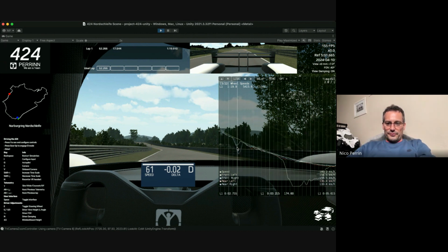135 kph, 133 for the rears, where the car is at 180. So the rear wheels are going 45 kph slower than the car. It's a fair amount of slip. The driver would call it a lock. He would say, I've locked the rear wheels.